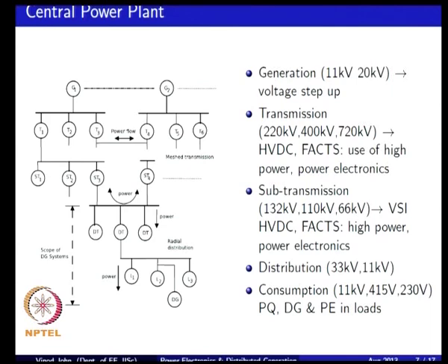and it is a non-renewable fuel, but it is distributed generation because of the way in which it is connected and the fact that it is distributed in two ways. One is it is connected at the distribution level or at the consumption level. The second thing is it is geographically distributed rather than being centralized in large individual centralized power plants. So, it is good to have clarity on the difference between the type of source and whether it is distributed generation or not. Just because you have one variety of source, it does not mean distributed generation.